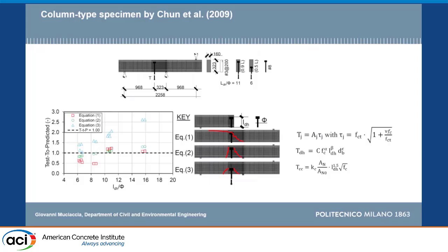What is shown? Of course, when the embedment depth with respect to the diameter is very low, concrete cone really governs. If we go far, we see that the prediction accounting for joint shear failure, the very simple analytical criterion on the acting mean stress, works quite well, and concrete cone seems to become unconservative, so we should account here for an effect of confinement of more than 2, to say that it is the size.